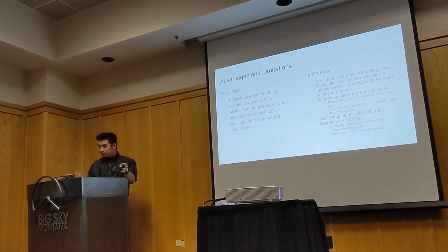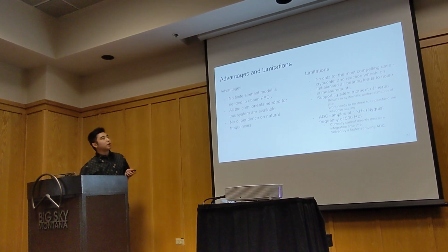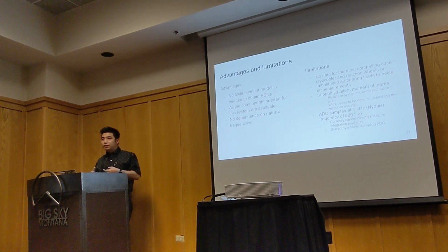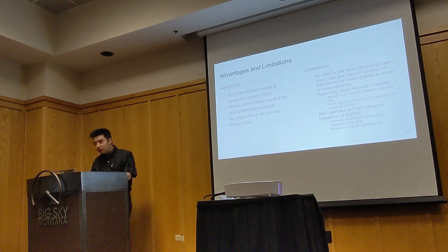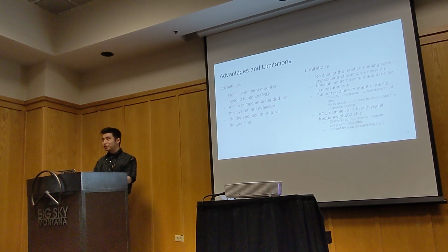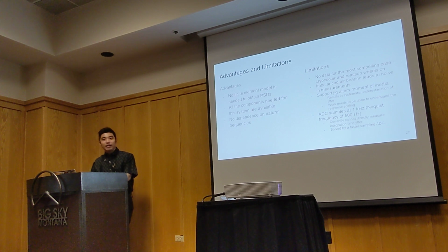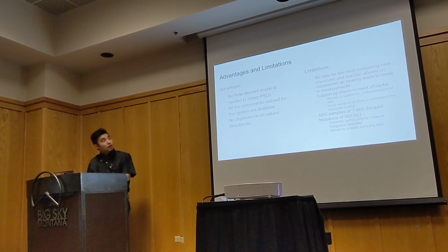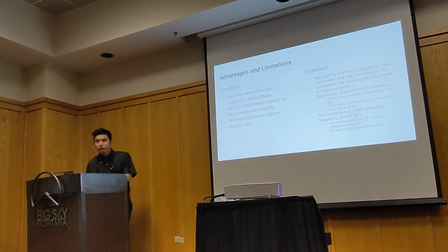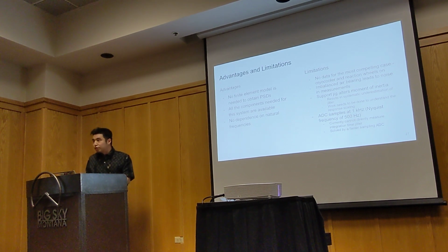And so wrapping up, some advantages and limitations of the system. Advantages: we were able to attain PSDs for jitter analysis without the use of a finite element model. All the components for this system are commercially available, and you can purchase them right now if you wanted to. And there's no dependence on natural frequencies for the system. A couple of limitations though: we don't have data for arguably the most compelling case, which is the cryocooler and the reaction wheels